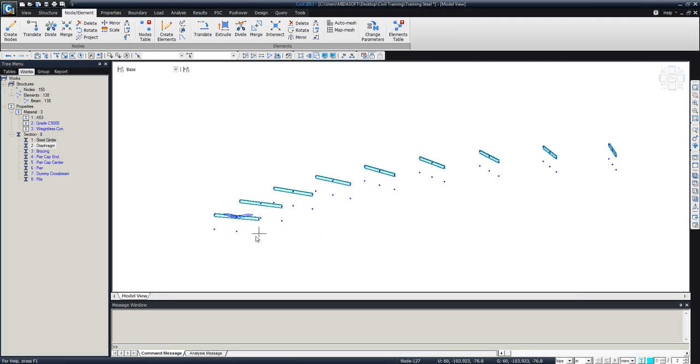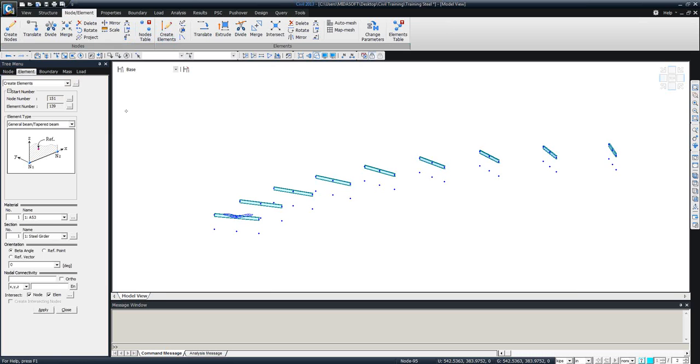And simply I can just create the other diaphragm down here and then create those bracings. Okay, so how to do that? Again, we are going to create element. So far we are just doing the modeling. You see that I'm going to use a lot of these functions, especially translate and extrude and also create. These are used a lot in this model for the modeling part.